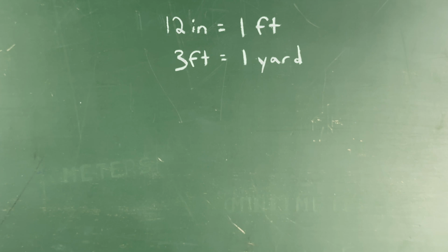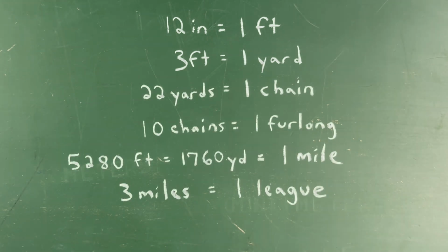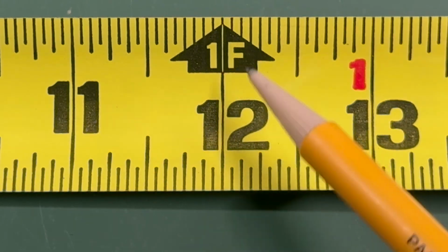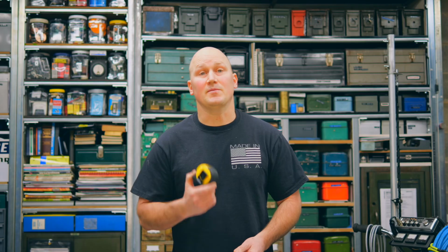When referring to a large number of inches, we group them into bigger units. 12 inches makes a foot, 3 feet makes a yard, 22 yards makes a chain, and so on up to and beyond a mile. Most trade worker measurements are made with feet, inches, and fractions of an inch. Measuring gets easier and faster with practice, so grab a minimum 1/16 graduated tape to get started.